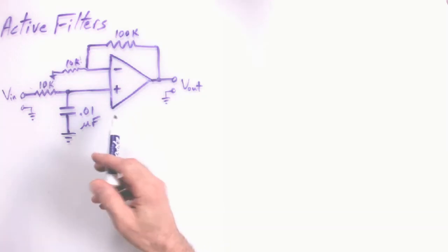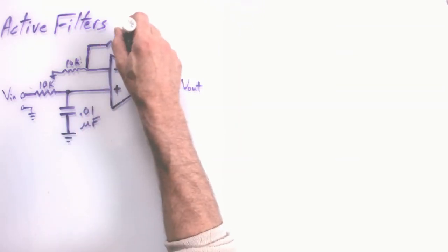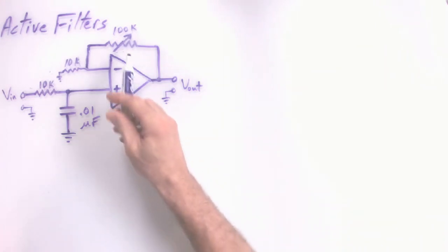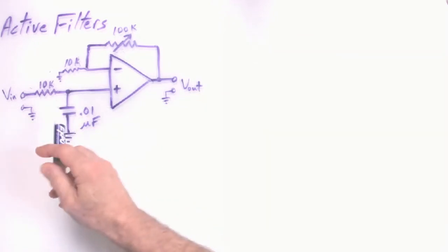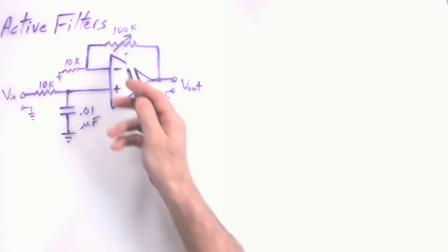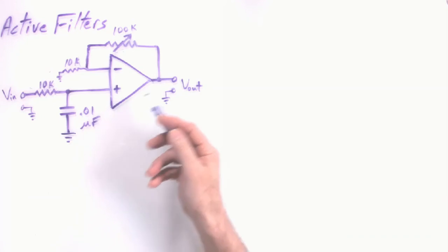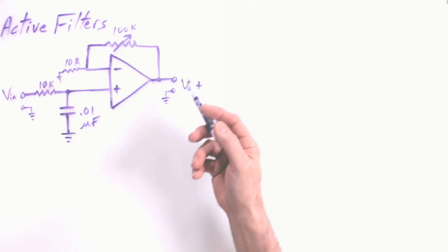And if we wanted to make the gain variable, there you go. If that's readable. Clean that up a little bit. So there I cleaned it up a little bit, just trying to show you that you can have the variable gain added to the low pass filter, and now you can adjust the amount of low frequency that you have here. It can be like a tone control or an equalizer of sorts.